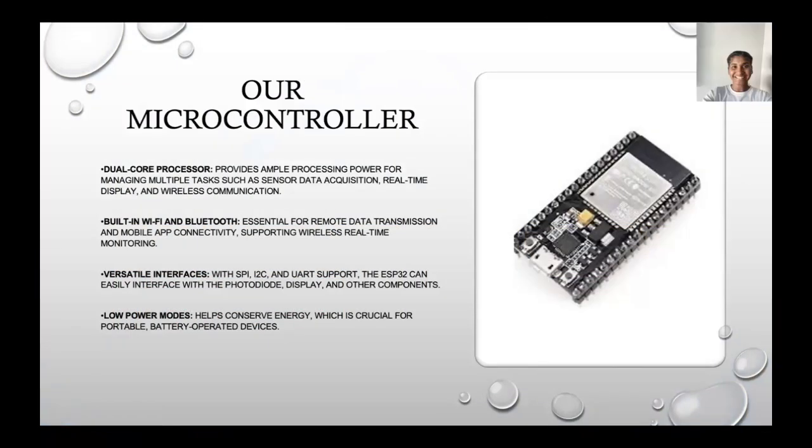Like O'Dane just mentioned, the microcontroller that was used by myself and Nihito was the ESP32 microcontroller. During our testing phases, when we were going through prototyping and trying to figure out how we would work with our IDE, the ESP32 was the most reliable and common source that was also user friendly for what we were trying to accomplish. It had built-in Wi-Fi and Bluetooth, which was very important because we wanted to be able to control our device portably so that we'd be able to set certain commands without being in the terminal.